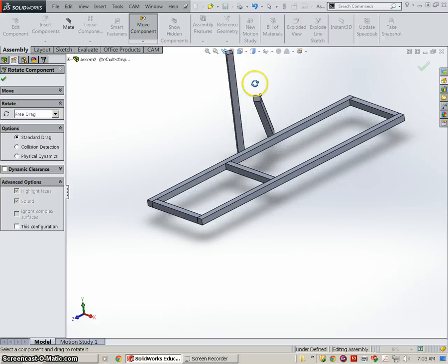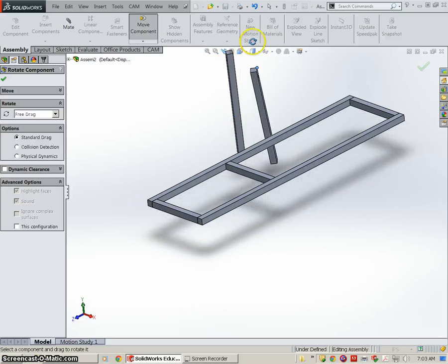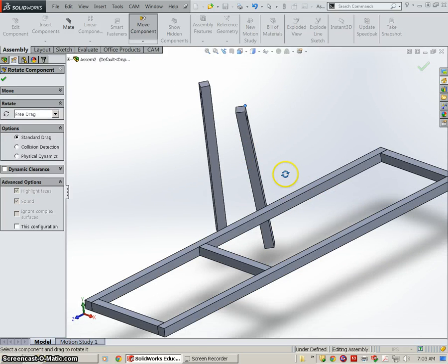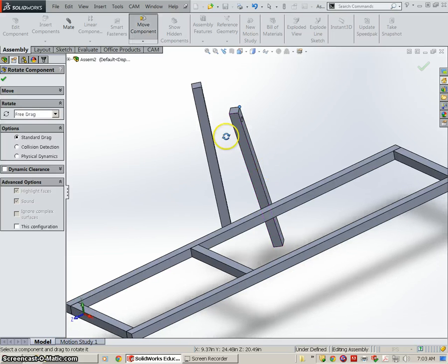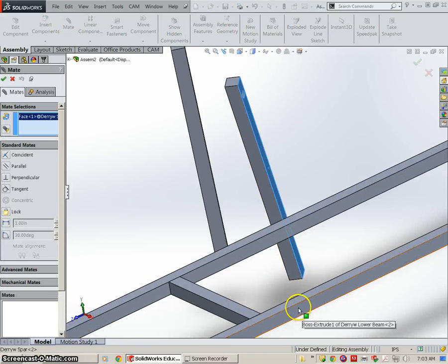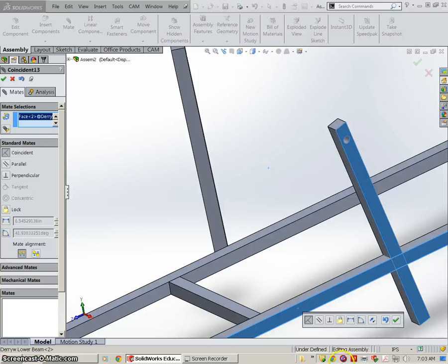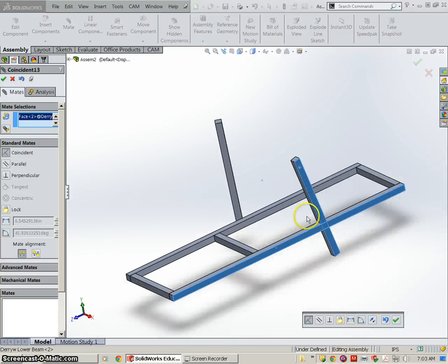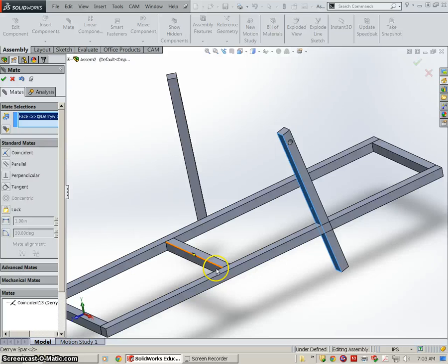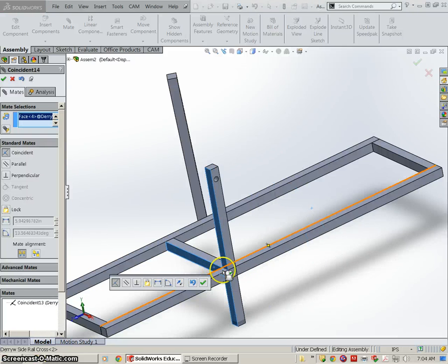own pace. Okay, these 2 spars have holes in them, and the orientation of the hole is important, so make sure you select the same faces when you go to mate yours together. I'm going to go back to my mate option and select these faces so that the hole is in the right orientation. Now obviously that's tilted, but we can straighten that out by selecting this face and this face. Oops, I need to click the check first. Excuse me. Alright, got those set.